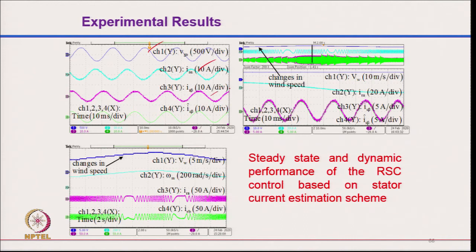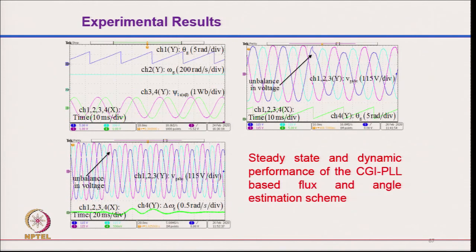Of course, these are intermediate signals corresponding to your stator side. When the wind speed is varying, you can see how the different quantities change as wind speed increases and decreases, and you can clearly see the rotor current. It passes through synchronous speed, so it runs at exactly synchronous speed like a synchronous generator, and it changes very smoothly over a wide range. The stator has a grid voltage that is already stable, and you are able to generate the varying power with that.